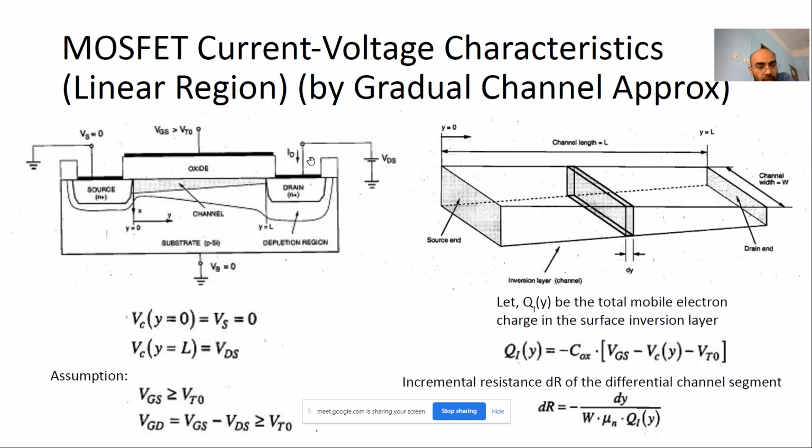So you just see them. What will happen? The voltage difference between the gate and the source, and between the gate and the drain, will not be the same. It will be different. The gate is at 2 volts, the source is at 0 volts, so the difference between gate and source on this side will be approximately 2 volts, whereas the potential difference in this half of the device will be approximately 1 volt.